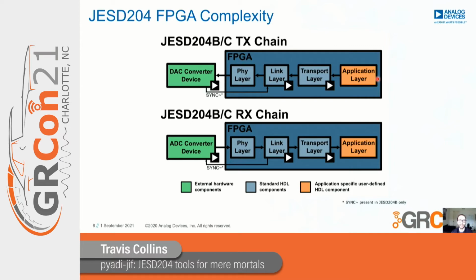Similar to any comm standard, you would have a number of layers associated with it that would take care of things like scrambling or error correction or link management, to make sure that things are coming up in a certain order, that metadata is inserted in the correct way, that you're correctly recovering clocks, and managing all those things. So you have these different layers that handle those different aspects of a protocol, of a frame or a header or metadata, and manage that system. So we're shifting that complexity from the layout all the way into the FPGA, into the ASICs themselves.